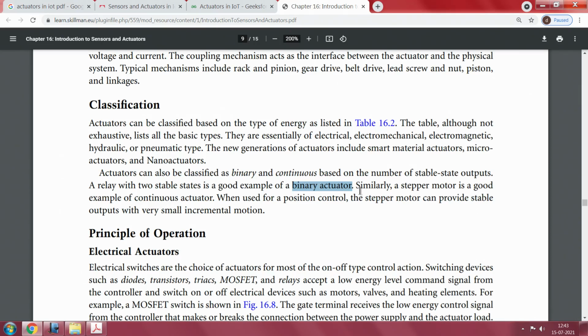You can also have a valve which is continuously opening, that means you control the power to a solenoid valve in such a manner that you open it, let us say half, you open it 1/4 and so on. So such valves exist, such solenoids also may be available, but by and large solenoids will give you on off, okay.